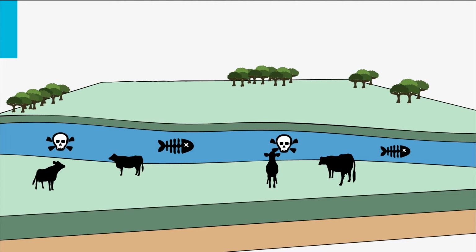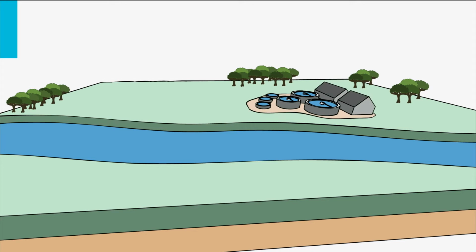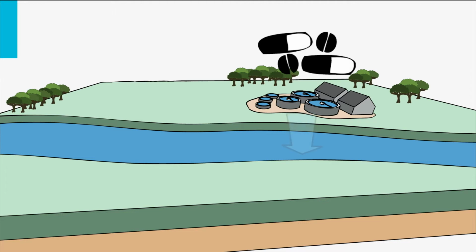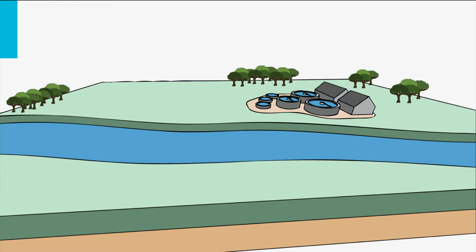In the past, the main focus was to remove organic matter from the wastewater. But more recently, advanced nutrient removal is applied to avoid eutrophication of the receiving water bodies. Future emphasis will be laid on the removal of endocrine disrupting compounds such as pesticides and pharmaceuticals to avoid accumulation of persistent organics in the environment.